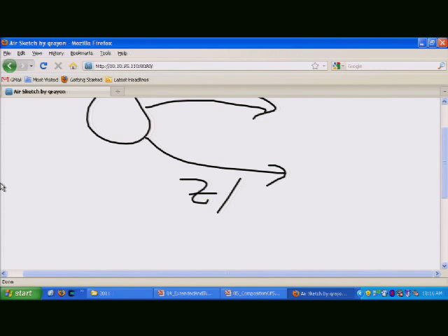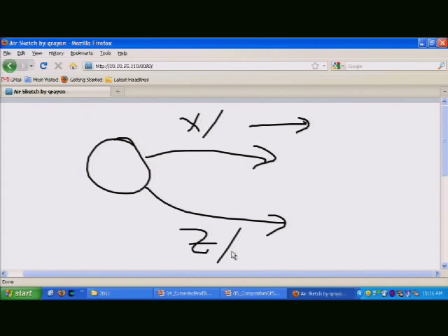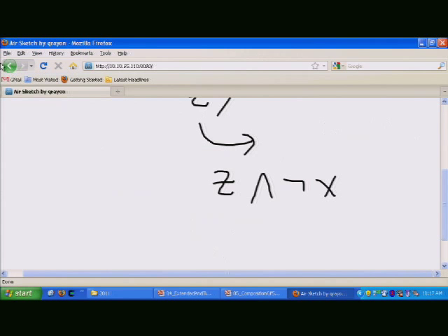Okay, but that means that explicitly in your code, you don't have this transition, but you have a different version. Instead of this, you have something which is saying if X is present, and then the other one would be different because it comes later. It would be if Z is present and X is not present, then you make the transition. The guard of the implementation would look something like that. But if the original model looked like this, it really doesn't specify what to do when both X and Z occur at the same time. And that leads to non-determinism.